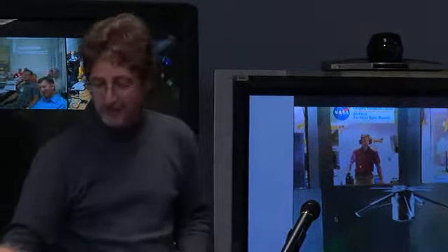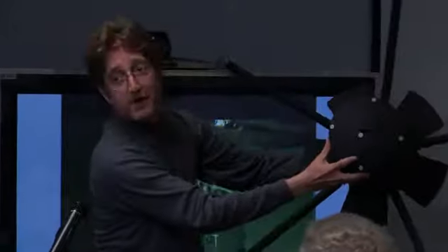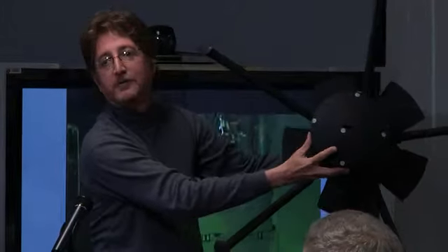But if I take the model and I place it in the spin tunnel, which you saw today, then the tunnel is my simulation. So that's the model, and the tunnel is my simulation. And in a sense, you can think of this as an analog simulation. It's not a digital simulation. So here's the model flying in the spin tunnel last year when we were working on this proposal. And we were interested in certain amounts of responses and angles. The way we get data out of this is there's a series of dots on the bottom of this, and there's a motion capture system that tells me the motions of the vehicle.